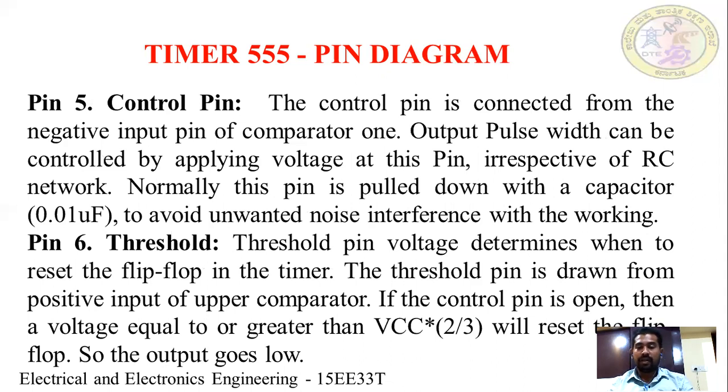Normally this pin is pulled down with a capacitor of 0.01 microfarad to avoid unwanted noise interference with the working.